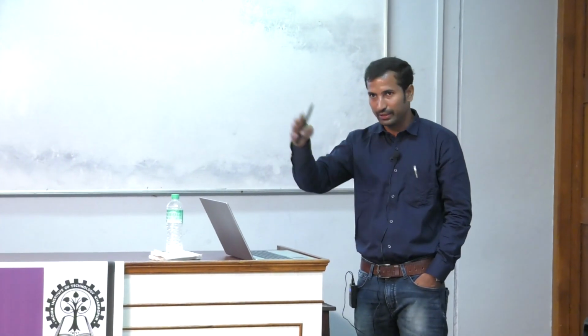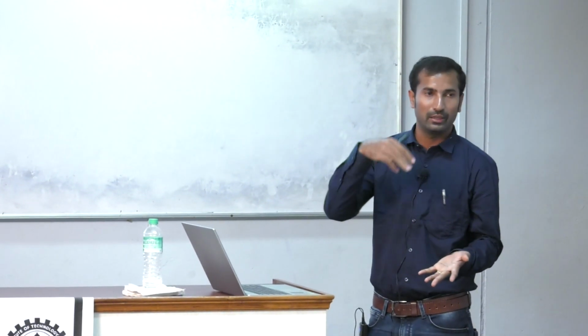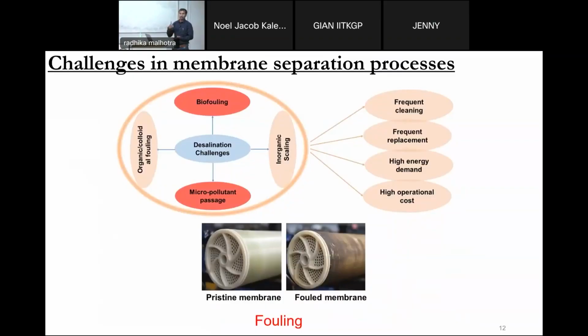It can be classified into organic and inorganic, where inorganic is in terms of scaling, and biofouling, and another issue which I was speaking of just before, micropollutant passage. Most of my research focuses on the highlighted ones, biofouling and micropollutant passage, because biofouling is a very serious issue.